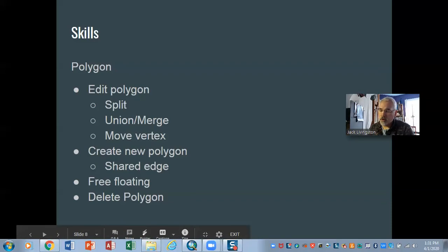Alright, this is the first of our videos for Polygon skills in the ArcMap environment. In the Polygon skill set, we're going to begin with some editing of existing polygons. In this, we're going to be using a move vertices and a split, and we'll also be doing a delete polygon. In this first one, we're not going to do the union and merge. That'll happen at the end. But again, editing is the first thing that we need to do.